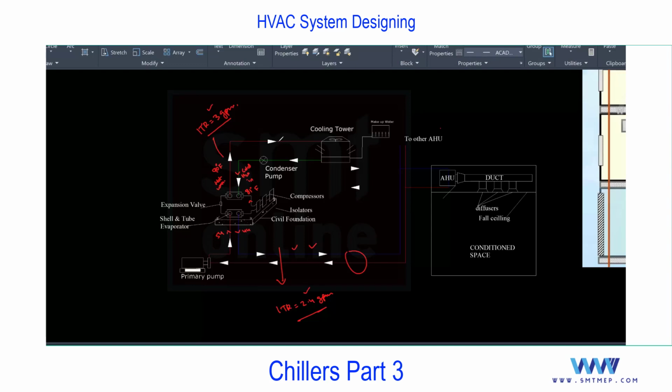So the hot water, in order to be used again to cool the condenser, will be supplied to the cooling tower. In the cooling tower, the water is supplied in sprinkler form. On the top, you'll find the fan, and the fan will suck the air from here. The air communicates with the water, and the hot vapor is separated from the cooling tower. It allows only the cold water to collect at the bottom. This is nothing but evaporative cooling. Continuously, the cooling tower separates the hot water from the return line of the shell and tube condenser, and allows the cold water to collect at the bottom.